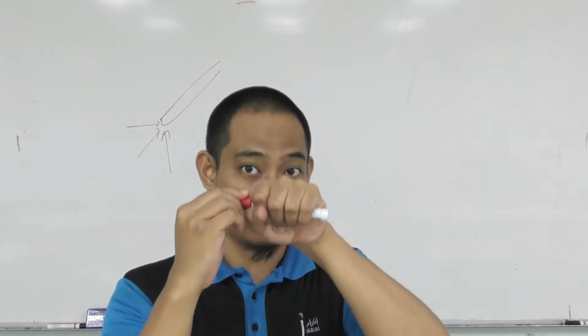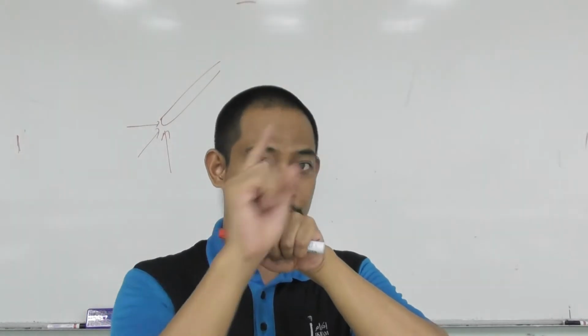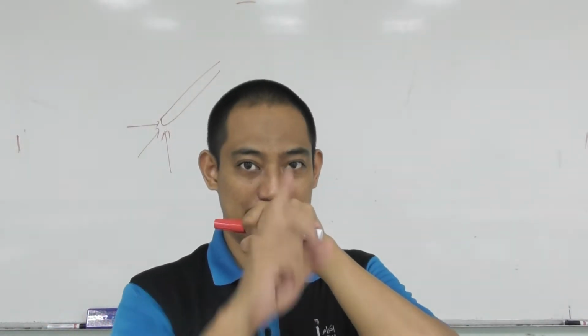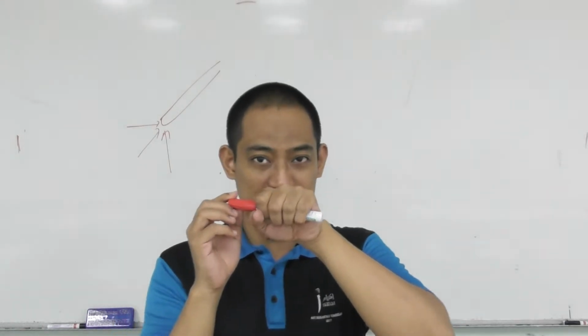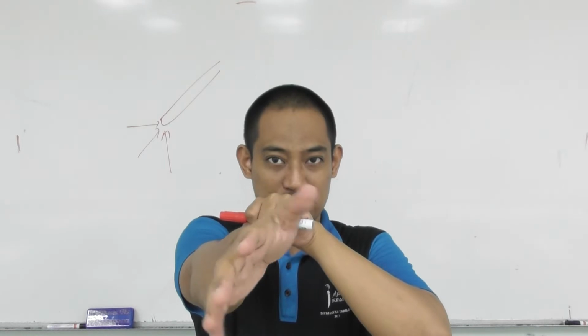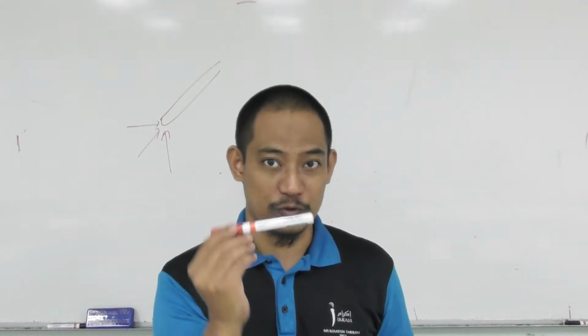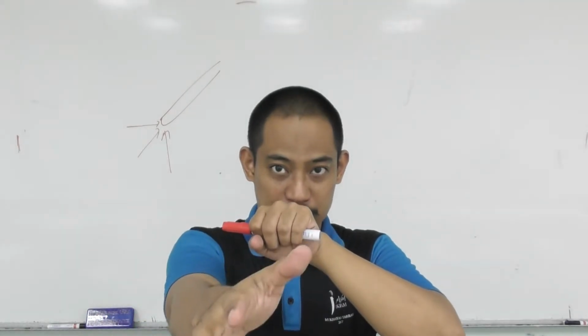Does it restrict movement in the z-axis? Yes, it does. You cannot move, so you also have a z force. So you have force in x and force in z in terms of the support reaction. Now, in terms of moment, does it restrict any moment about the x-axis, rotating like this? Of course, you cannot rotate this way because it's captured like this. So you also have Mx there.